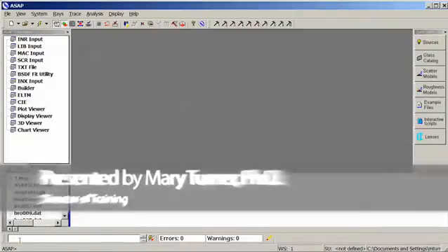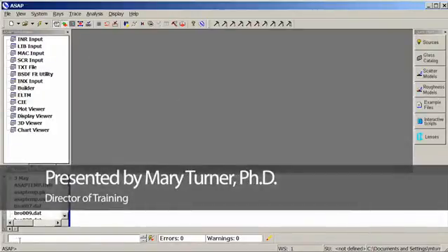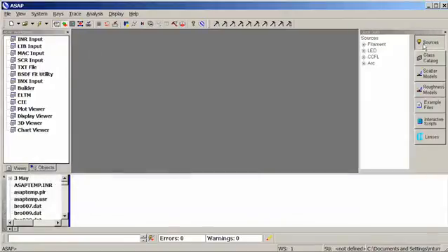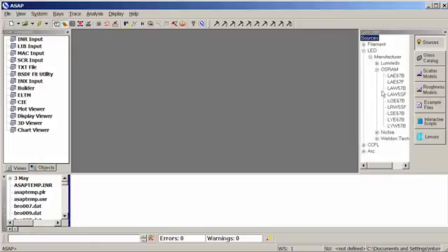With the Bro Light Source Library, we can import a model, both physical and radiometric, of a wide range of commercially available light sources. In particular, we're going to look at an Osram LED, part number LAW5SF, and we're going to look at the process for bringing this information into ASAP, including generating the rays from this source, as well as creating ASAP script files that will help you use this within your current design or any future design you might choose to create.